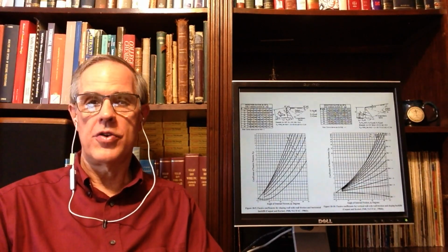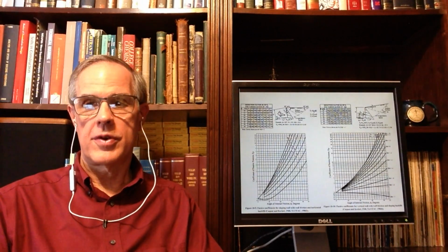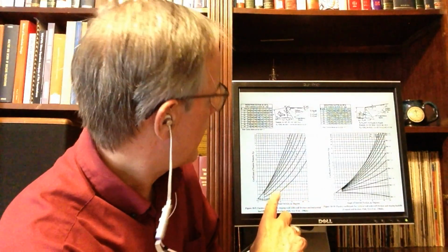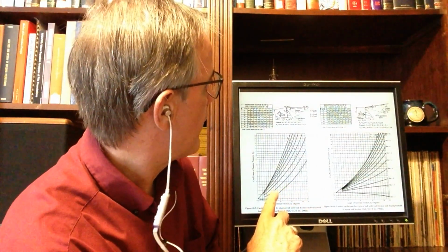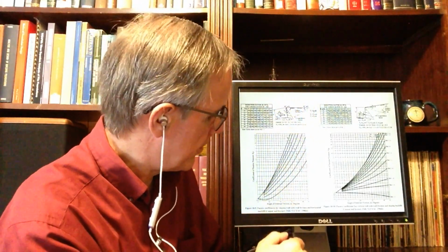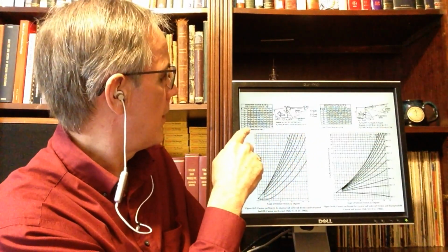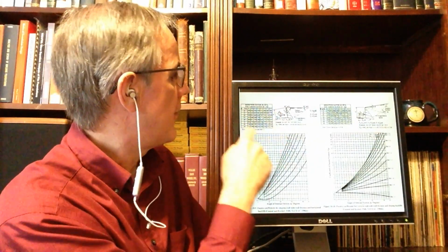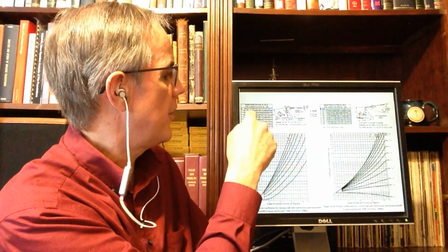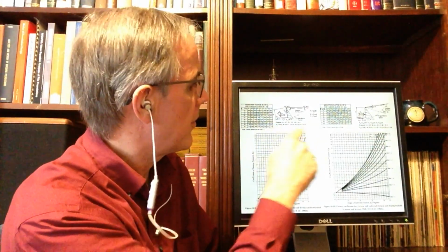These are the charts in your book, which are used for AASHTO. There are two charts actually. The one on this side basically assumes that you have a level backfill, and you vary the phi and the angle of the wall, and you have different results. And then once you get this, you have to turn around and use a reduction factor to get from this through this to there. And you've got little examples here which you can follow.